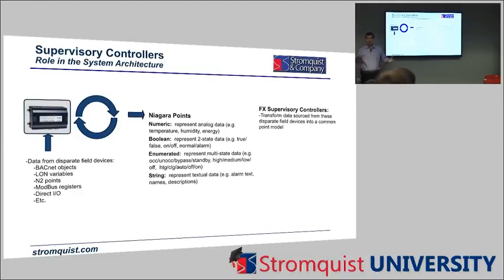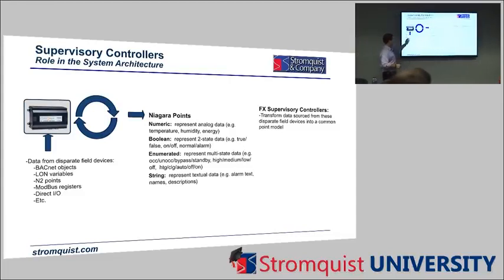All right? So they've come up with one unified language. They can essentially bring in BACnet, LAN, whatever it is, into the Jace, turn it into a Niagara point, and then everything on that Jace level that gets pulled in, all those controllers and all those points and set points and space temps and pressure variables and all that kind of stuff, is turned into one of these 4 Niagara objects, which is that common language.